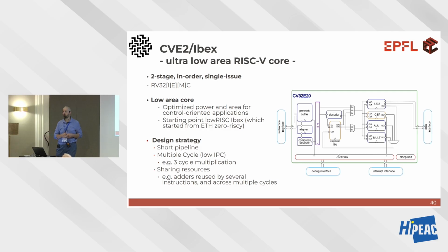Yes, depending on the encoding, exactly. But once it's fetched, that's when you know the content of the memory, right? So in an uncompressed instruction, the first 7 bits already tell you if it is a compressed or non-compressed instruction. Even better, the first 2 bits. But you know it only once you receive the data. Yes, of course.